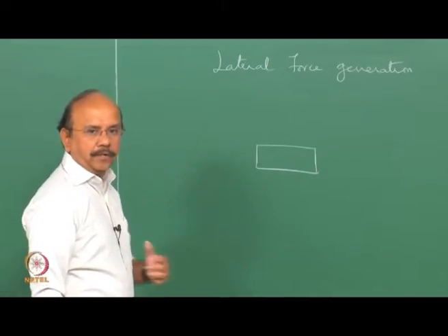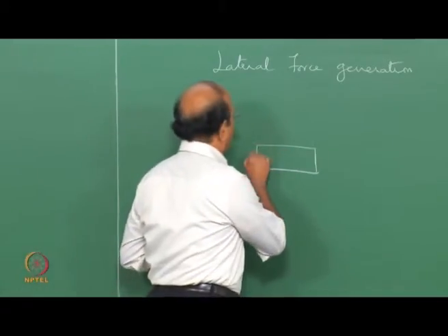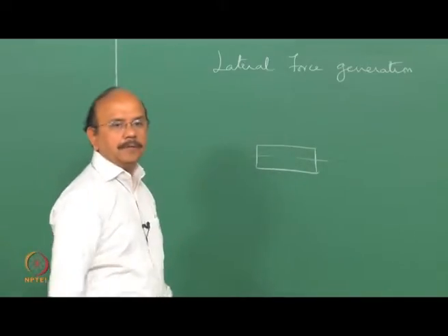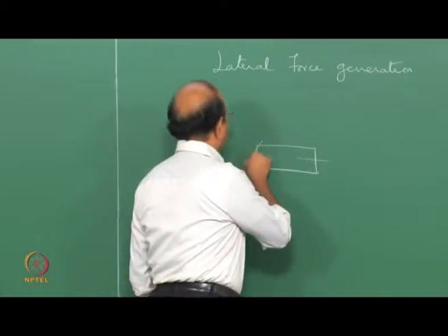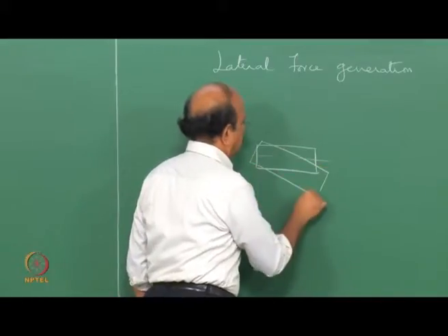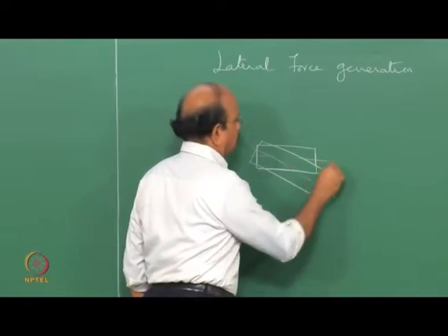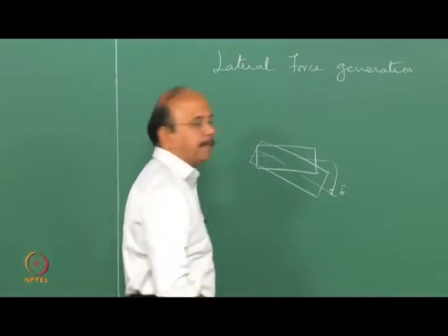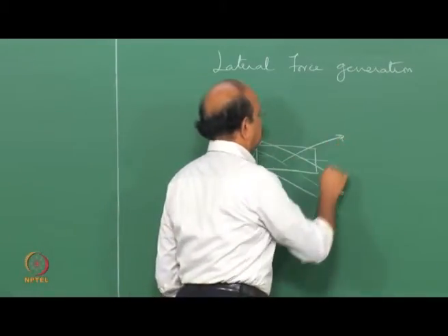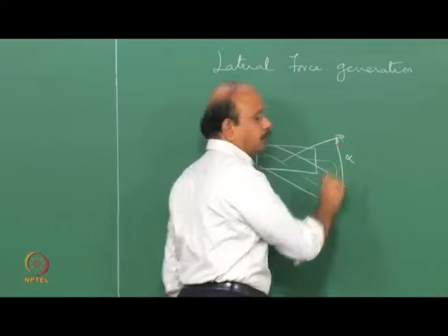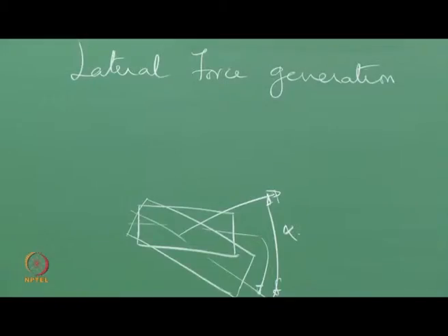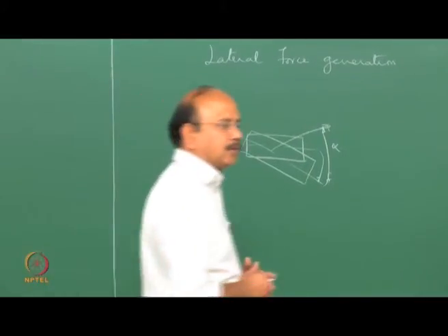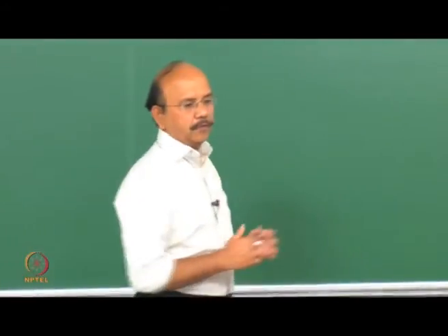So if this is the straight running tire, and this is the central part, and then you give a steering input, which we said is delta, actually there is a slip angle produced, and so on. And we saw that the distortion causes that centripetal force that's required in order to sustain the centripetal acceleration. In other words, it cancels out the D'Alembert's force called the centrifugal force.